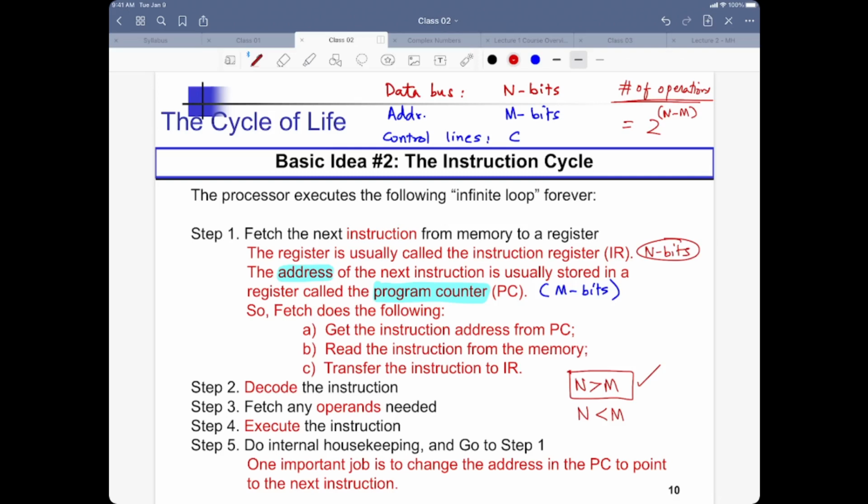Does it change depending on instruction? No. It is always going to be the same thing for all the instructions. Second one is decode. Decode is Zach trying to understand what the professor wrote on the piece of paper. What is the computer doing? It is trying to look for 0, 0, 0. You have said opcode is 0, 0, 0. What does that mean? Decoding that opcode field and then consequently sending out all the other control lines accordingly. That's what decode the operation means.